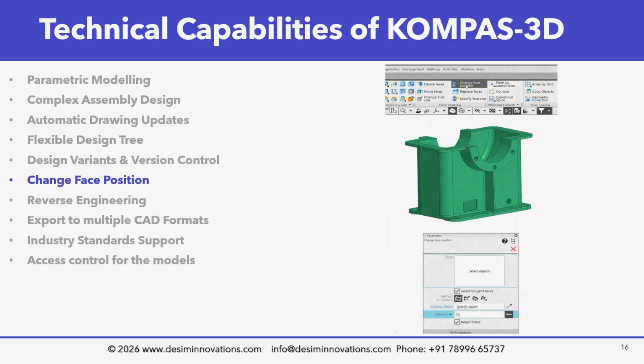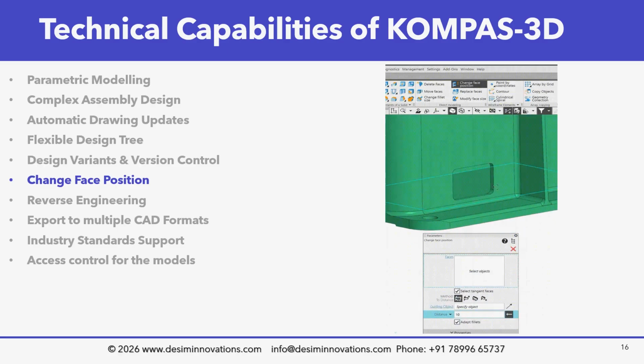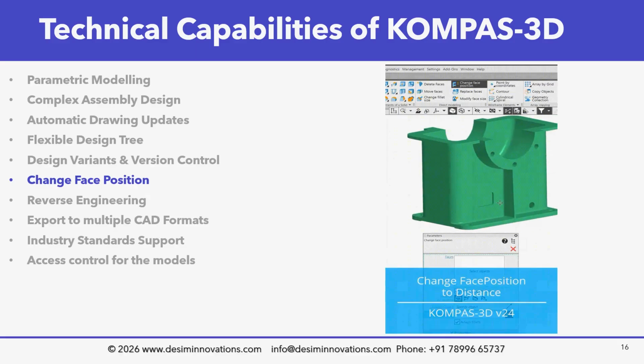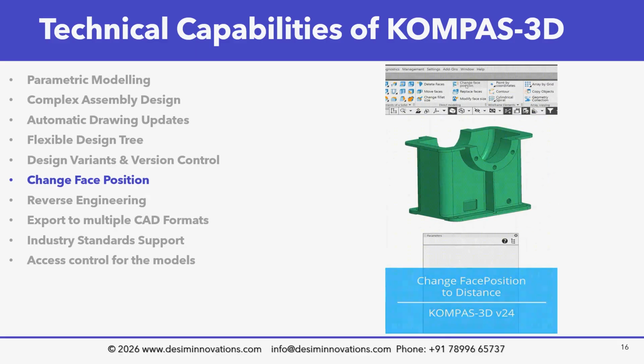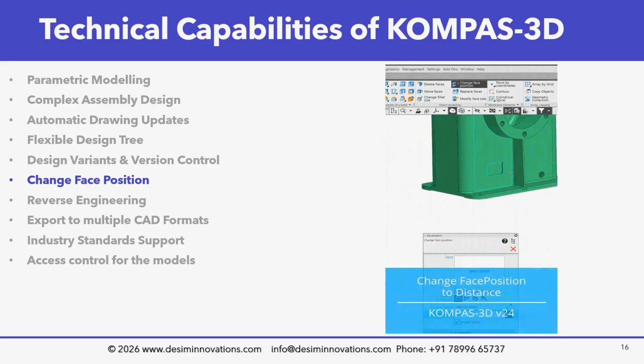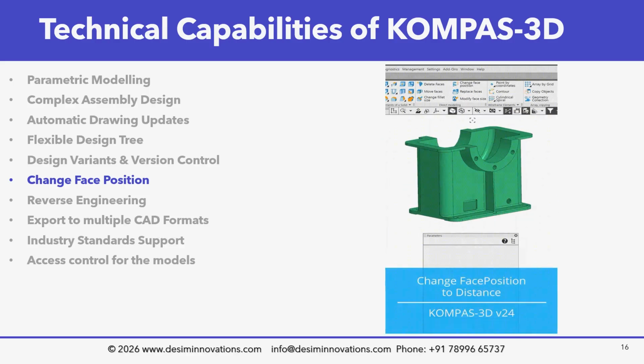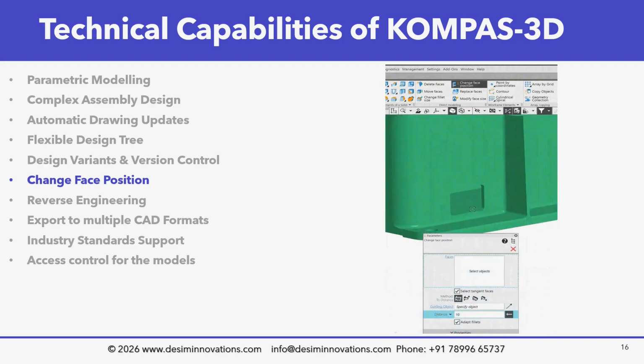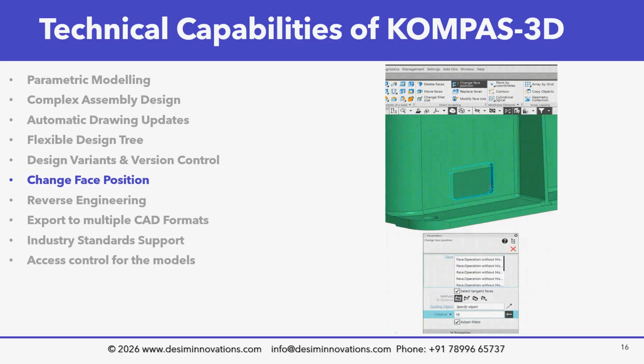And you will also find a feature called change face position, which is useful when you need to make quick modifications without rebuilding the geometry, especially when you import STEP or IGS files. If you need to modify or move some of the faces, this feature really helps by letting you move the faces or change the face position without editing the sketch or creating from scratch.